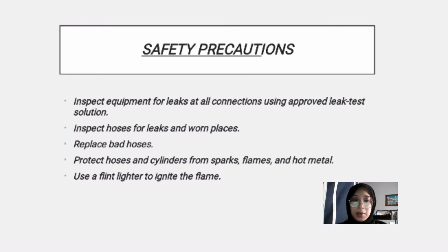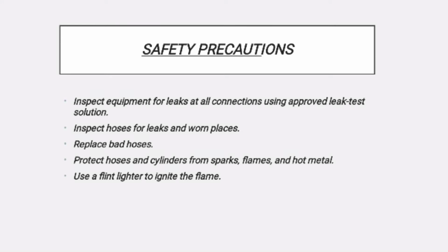Next is safety precaution. Inspect equipment for leaks at all connections using approved leak test solution. Inspect hoses for leaks and worn places. Replace bad hoses. Protect hoses and cylinders from sparks, flames, and hot metal. Use a flame lighter to ignite the flame.